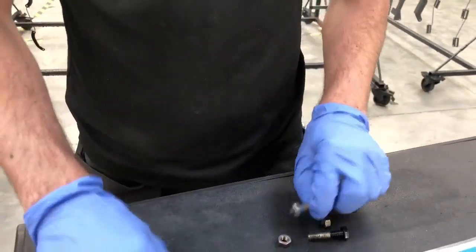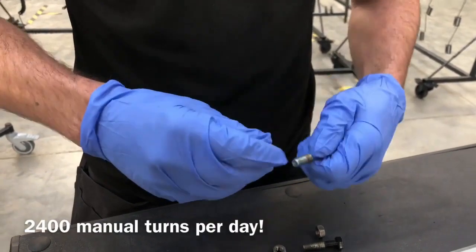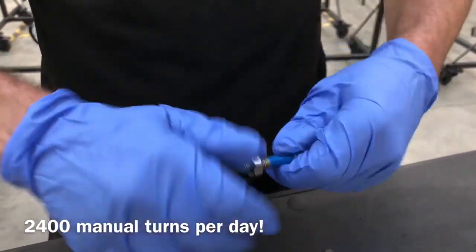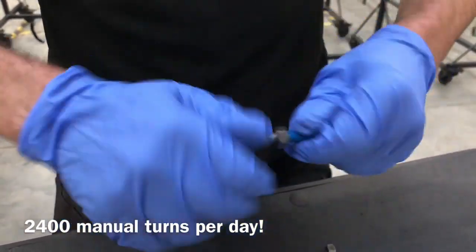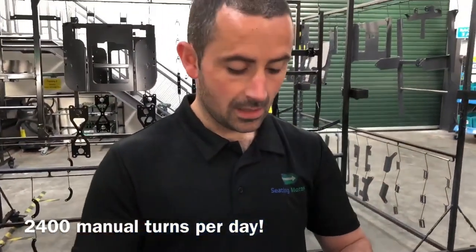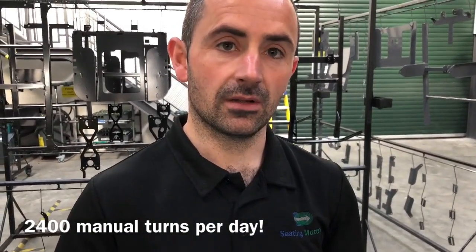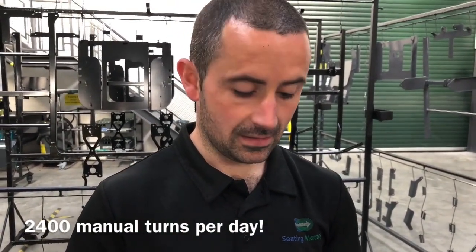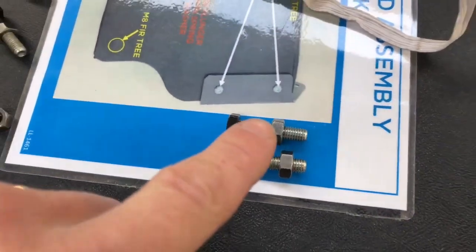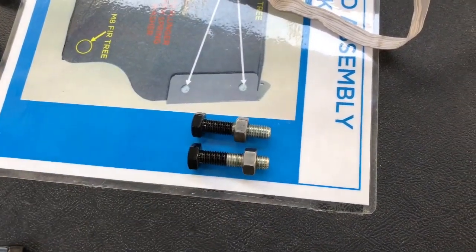If we watch the detail, we'll count the number of turns, because every single turn is waste. So 1, 2, 3, 4, 5, 6, 7, 8, 9, 10. So 10 turns. And how many nuts at a time? We have like 240 nuts a day just for all our chairs. 240 nuts a day by 10 turns. Okay. So there was also the possibility for inconsistencies. Some nuts could have been threaded more than others depending on who was carrying out the task.